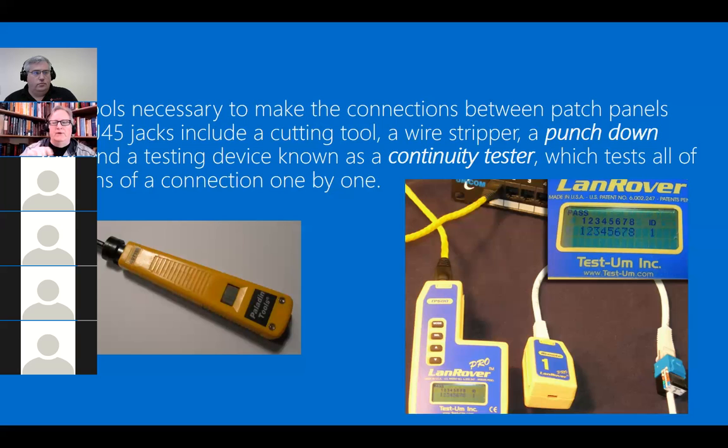Sometimes the blades are different, and they're under more stringent rules, so when you're using them you've got to have perfect crimps, clean cuts, and you don't want a cheap type of medium. The medium itself can cause you headaches, and it has to be specified Cat 8 because of the twist if you're using copper. A lot of cabling companies don't tell you this, but sometimes the wires are made out of nichrome or some cheaper alloy that is still marked as a network cable but is absolutely useless at the high gigahertz rate. So you just want to be careful that you get truly certified solid copper or solid gold connectors when you're using it at that level.